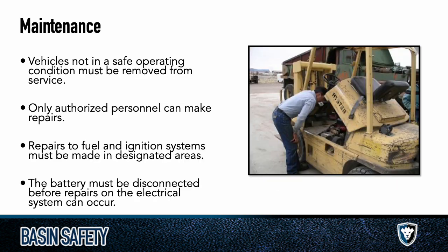Maintenance is a required thing. In forklifts, just like anything with hydraulic systems, they do need inspections, maintenance, and there are certain hour numbers where certain things need to happen. The instruction manual is going to tell you that, and that's why it always has to be on the vehicle at all times. So if it's not in safe operation, shut it down, lock it out.